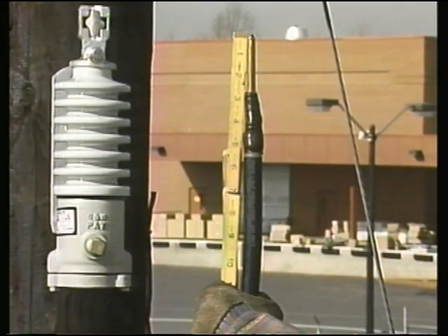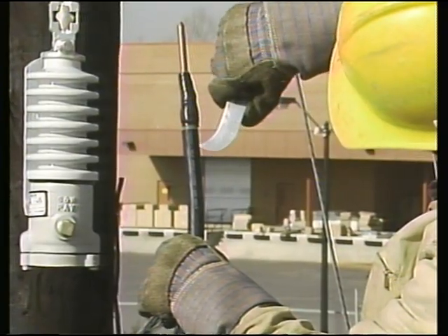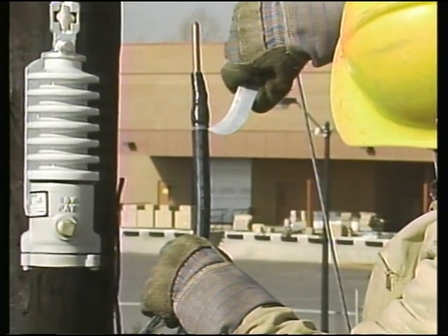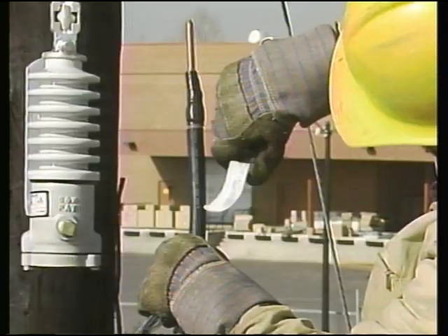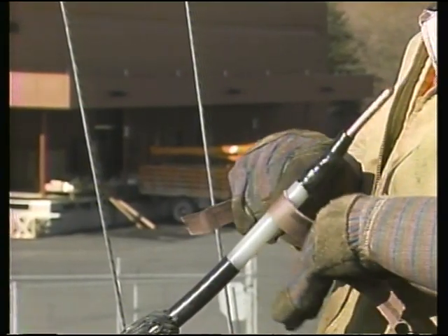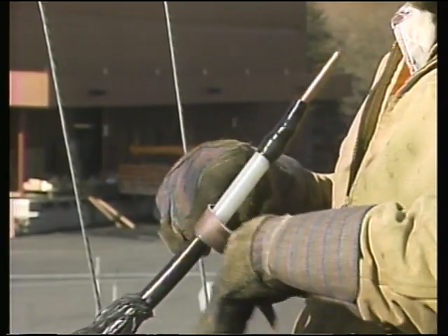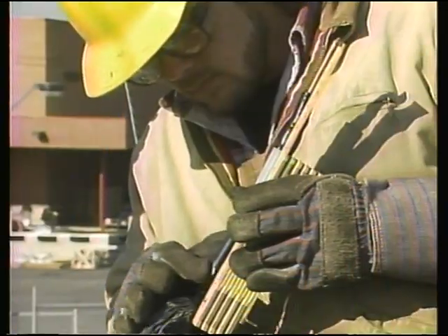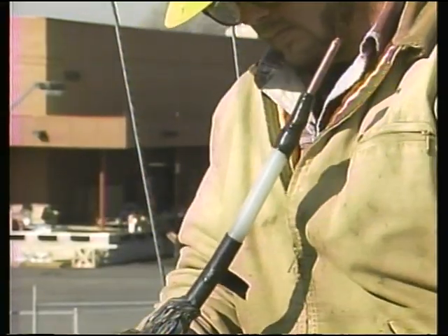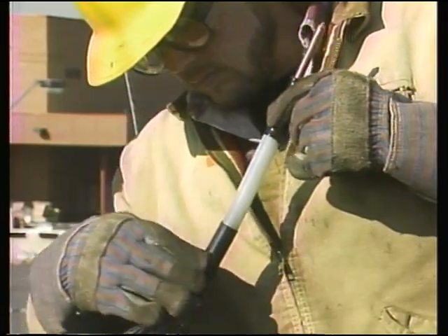Now, a measurement is taken from the end of the connector, and the semiconductive insulation shield is removed. The workman is careful not to damage the primary insulation when he removes the insulation shield. Then the insulation area is sanded to remove any semiconductive particles or contaminants. Next, the cable is measured and a tape mark is placed on the cable to indicate how far into the terminator the cable must be inserted.